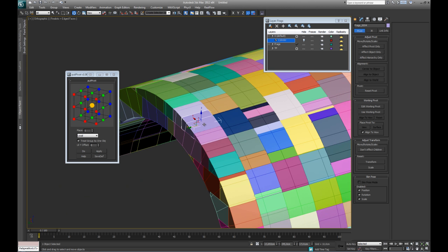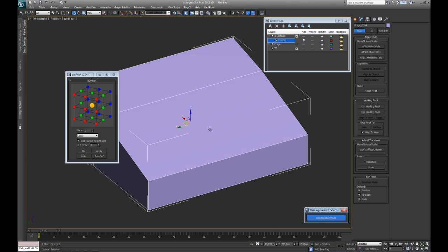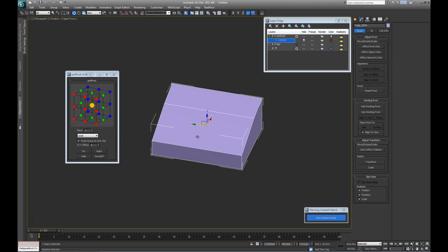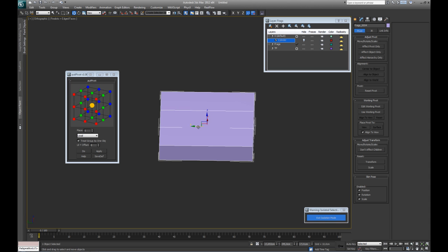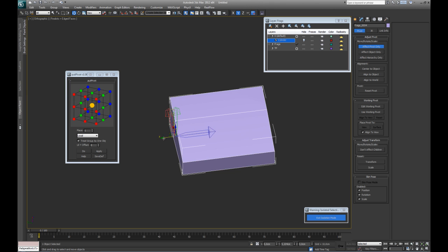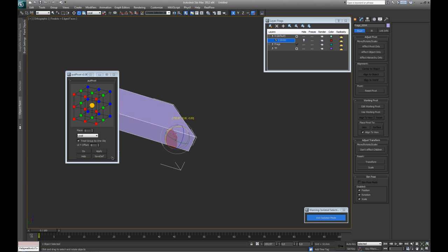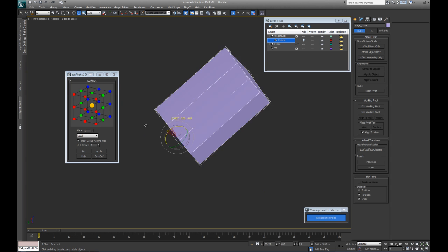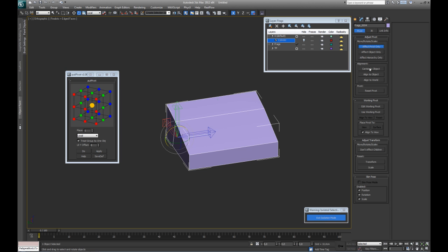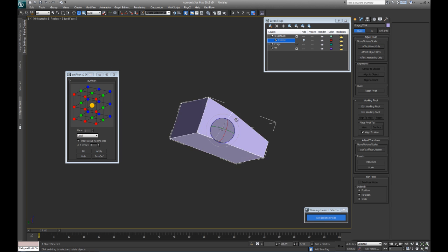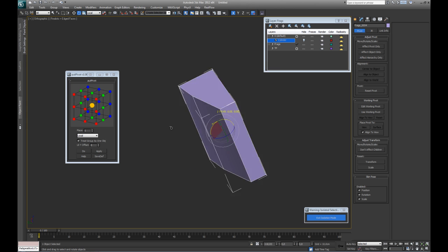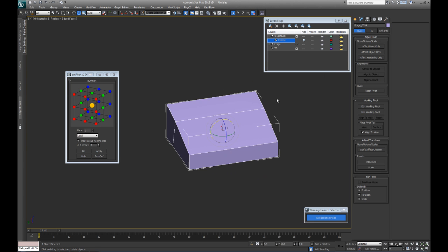For example, I have this little part selected. I'm gonna isolate it so we can work with it. So what I actually want is to have the pivot point placed like a door hinge, meaning I would like to do this, for example. So when I rotate it, and I'm just gonna pick local to make sure that I do it in local, you can see this has the kind of door hinge effect, and that's kind of the base of this build effect. If you put it in the center as it is now, you would just have this kind of flip effect, and that's not really what we want.